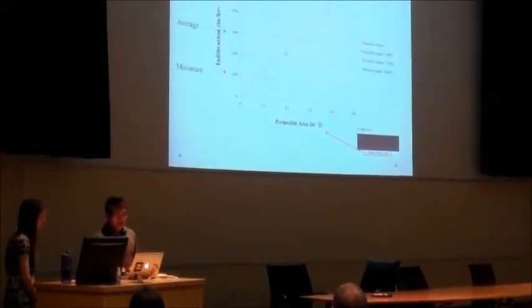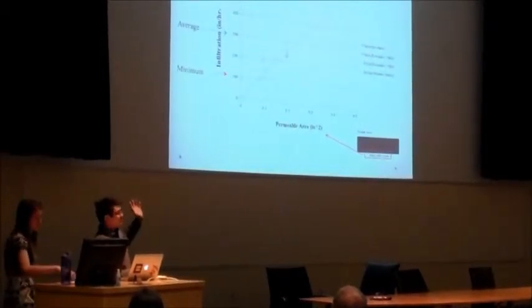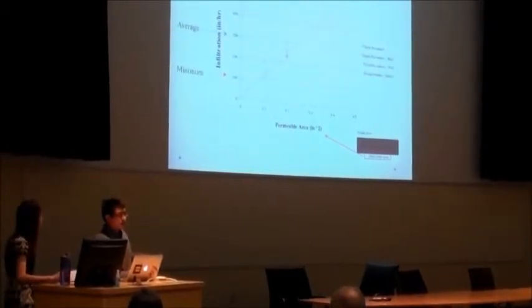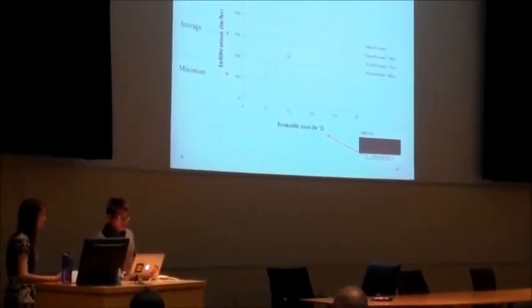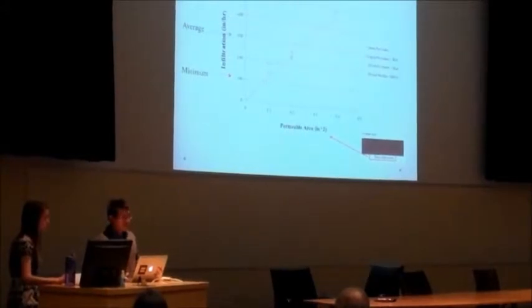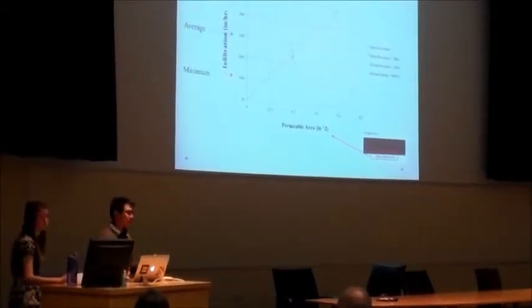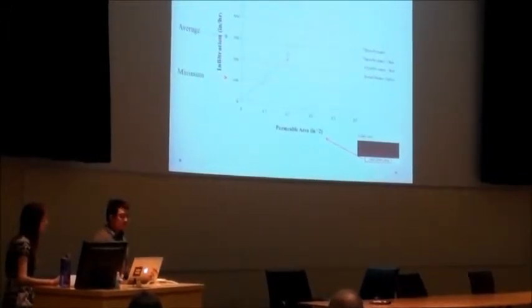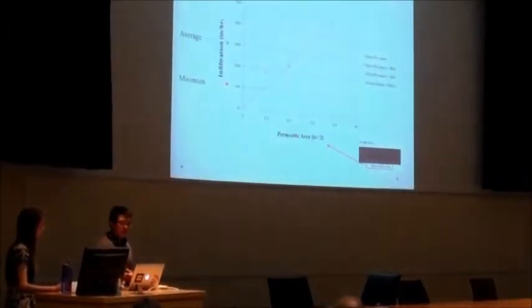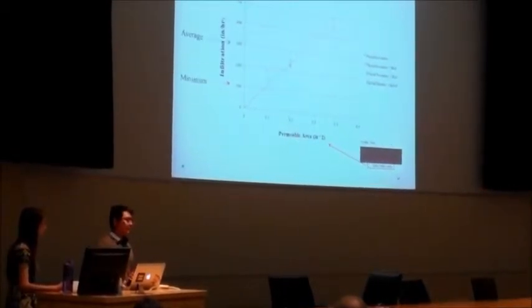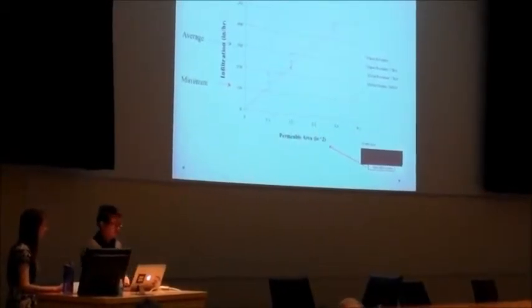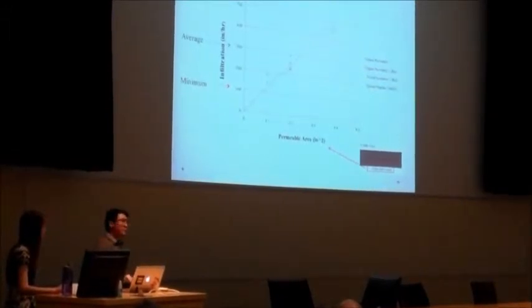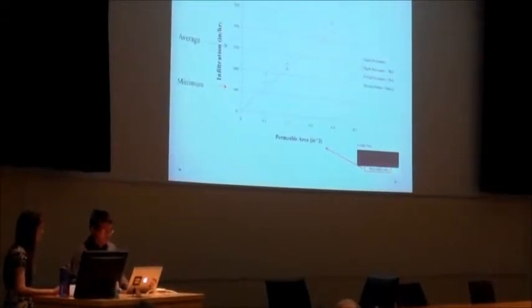of its performance. And the pavement with the foundation underneath it, to better reflect how it would do on the field, it didn't seem like it varied very significantly from just the pavement by itself, which is good. And we had a range from about 150 to nearly 500 inches per hour, which is excellent considering the average pervious concrete pavement on the market drains at about 300 inches per hour, and a new standard will call for a minimum of about 100 inches per hour, with failure being at less than 10 inches per hour, way down there.